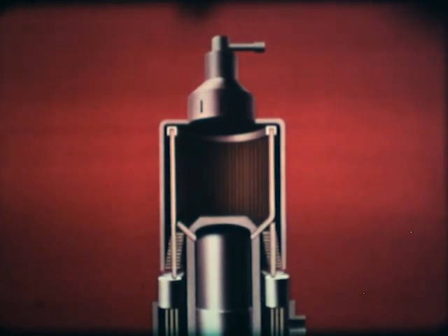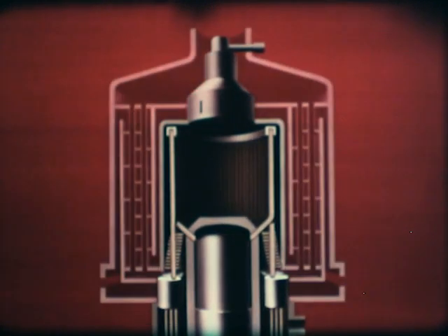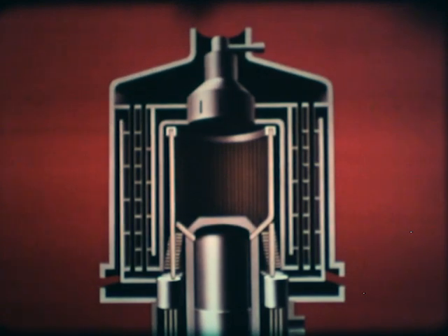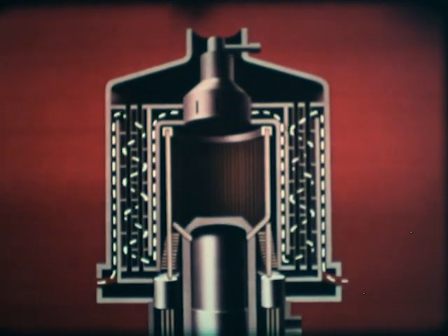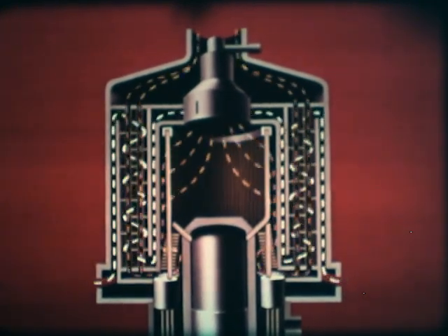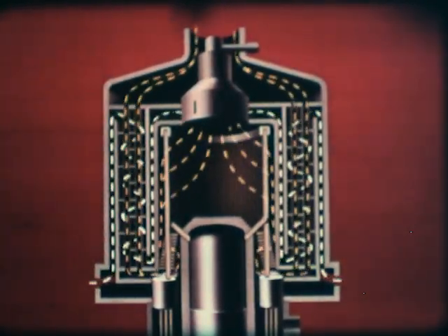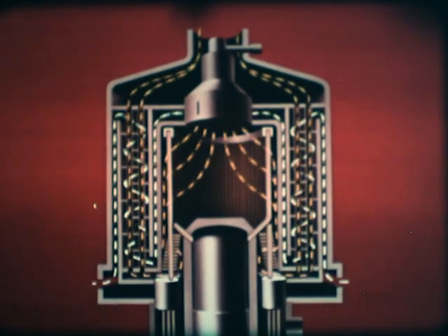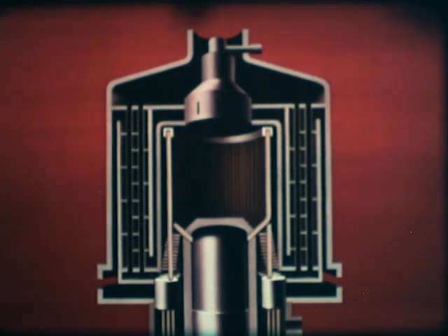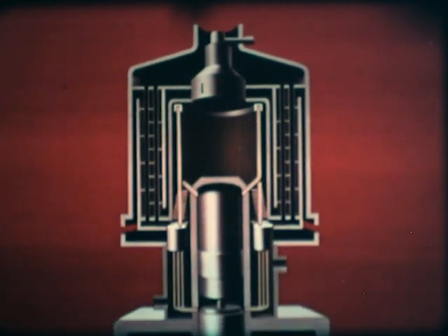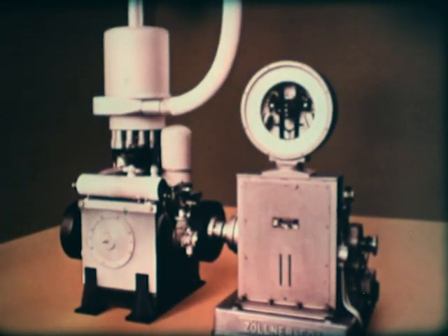The efficiency is increased by using a preheater. In this, the air is led to the burner against the flow of combustion gases, absorbing heat from them and thus reducing chimney losses. The heating system, being external, is very flexible indeed. It can be adapted to use nuclear, solar, or stored heat energy. This is the end result.